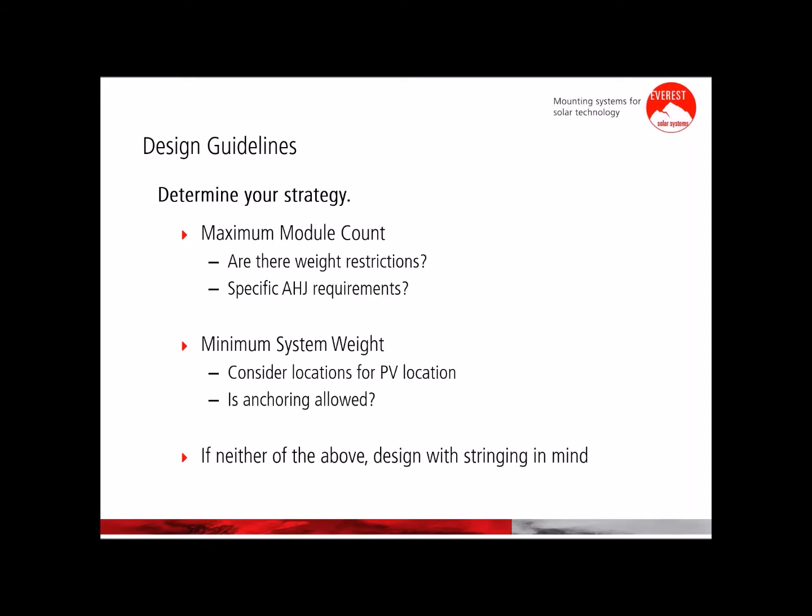We want to make sure we're not putting too many modules on the roof to a point where there are modules where a fire aisle needs to be. So that's something to keep in mind when going down that particular road using that strategy.